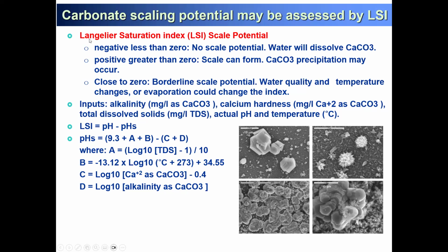So how they detect this is based on the LSI scaling potential, Langelier saturation index. You can see the LSI scaling potential from the software, but the theory behind it is: negative, less than zero, means no scaling potential. Water will dissolve calcium carbonate, so you don't have any scaling issue. But if this LSI value is positive, greater than zero, scale can form, and calcium carbonate precipitation may occur.